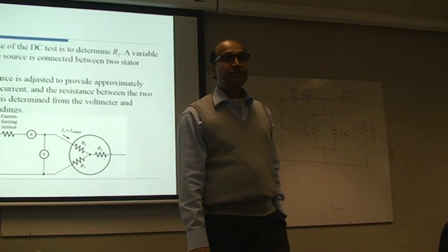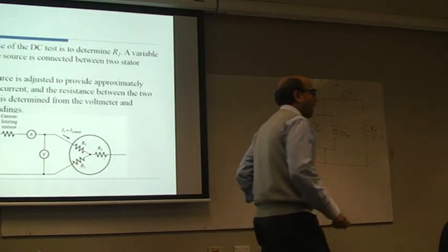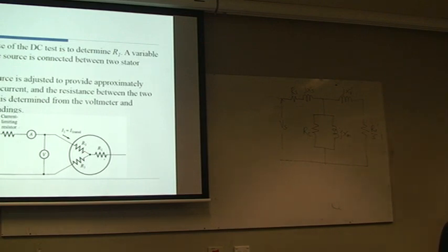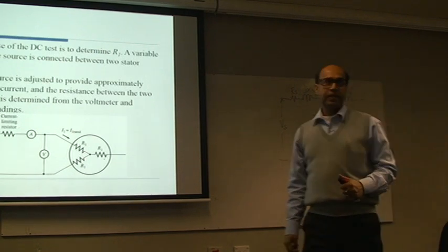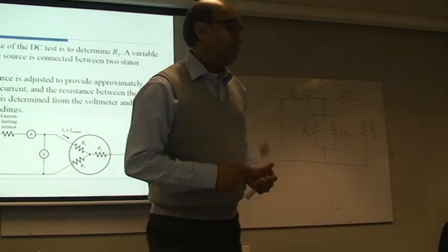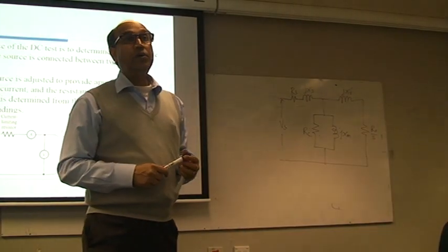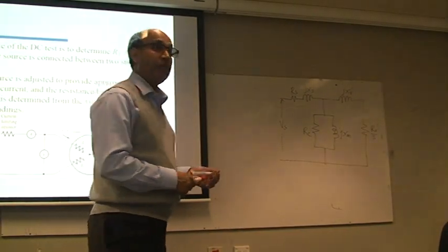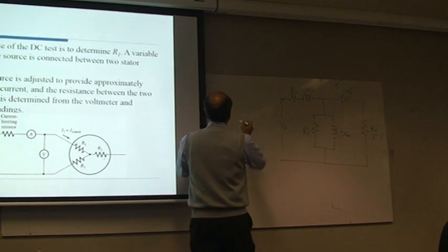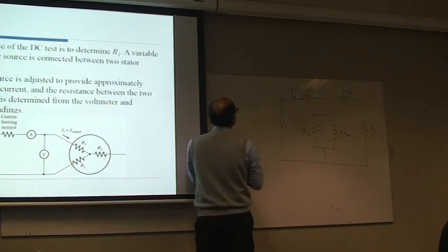Run a current through it and see what DC voltage. Yeah, the simplest thing you may say, I can actually take the terminal and measure by ohmmeter. Okay, it's still good, but you are talking about 3-phase. So how many terminals you have got? You have got 3 terminals, isn't it?